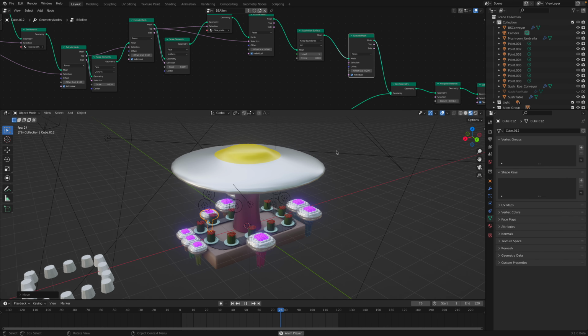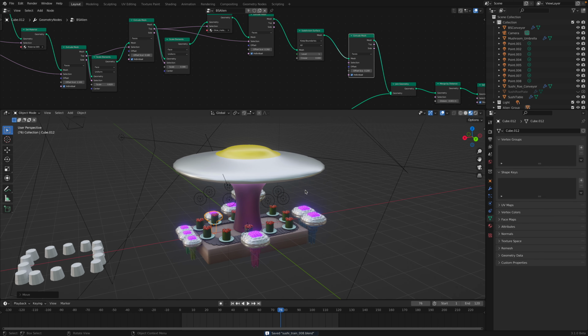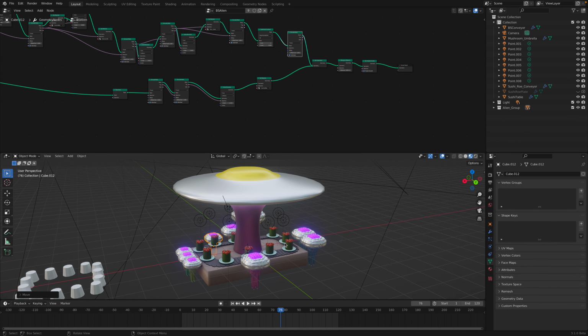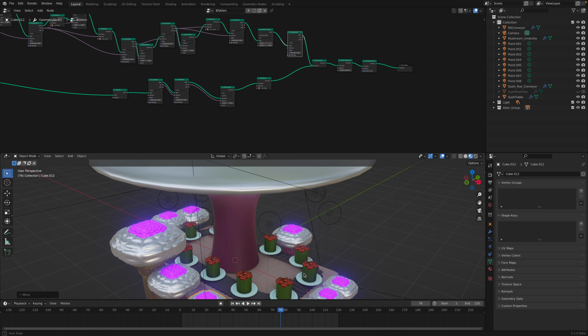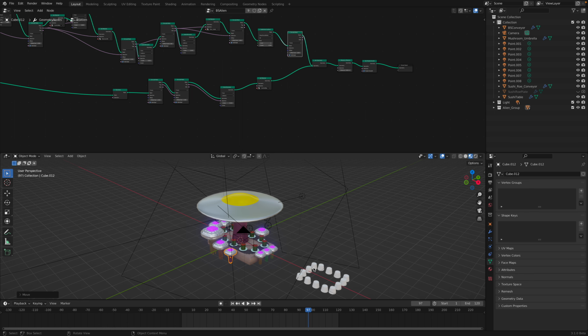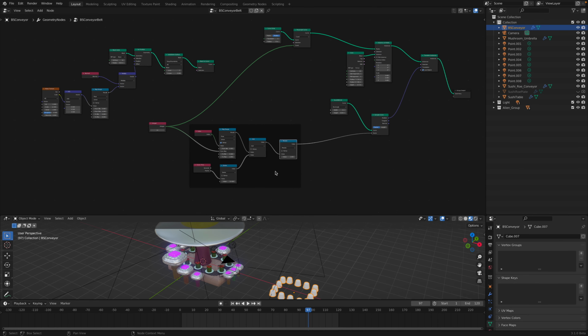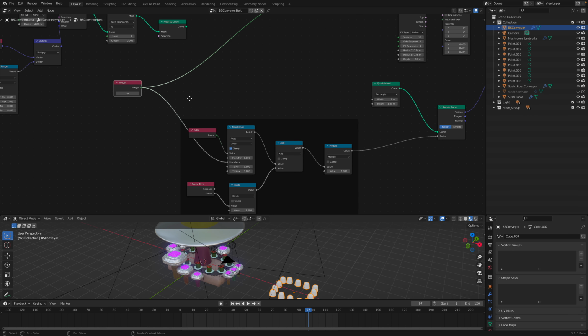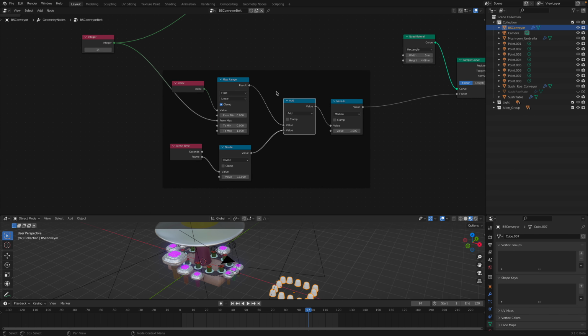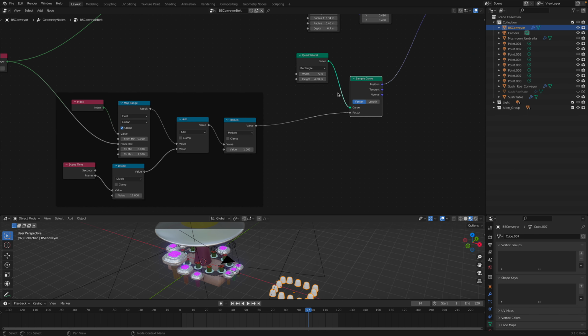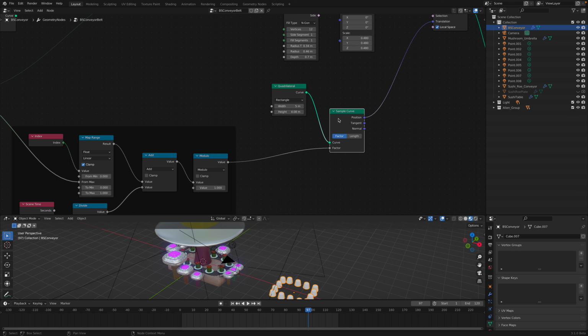So it's all procedural. I mean, this one seems complicated, but it's not really. Mostly just extrusion, and then just instancing, same thing. Just the conveyor belt is slightly more complicated and interesting. This is almost like you are making a field, like a particle simulation, just using a little bit of math, and we are resampling the curve. I think this node is quite powerful. I don't know 100% what this actually does, but you can sample a curve position, I think, based on this factor. There's a length and there's a factor.